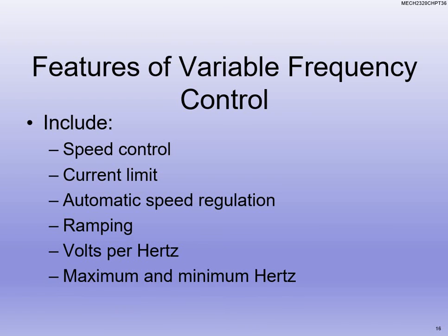A very big advantage to this is we can do automatic speed regulation. Very important. We have speed sensing devices on everything, so everything can be switched automatically at once. If you're on a conveyor and we put weight on that conveyor, things are going to change. We want the speed to remain the same. So we want to use a VFD so it can regulate the speed and automatically make the changes necessary so that everything works.